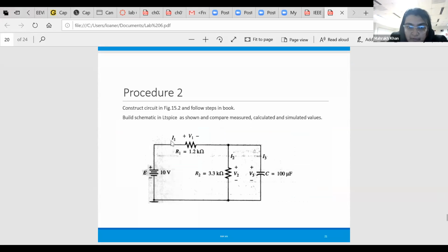So it will be R2 divided by R1 plus R2, and whatever the voltage here is will be the voltage that accumulates here. And what do you think, once the capacitor is open, what current will be flowing in the circuit? Will any current flow in the circuit? Once the capacitor is open, only I1 will flow here, right? And this current will not flow in the circuit.